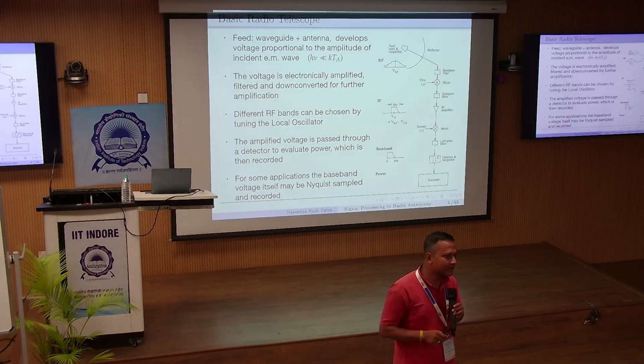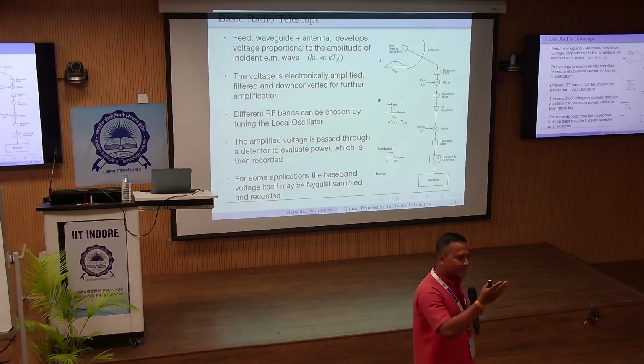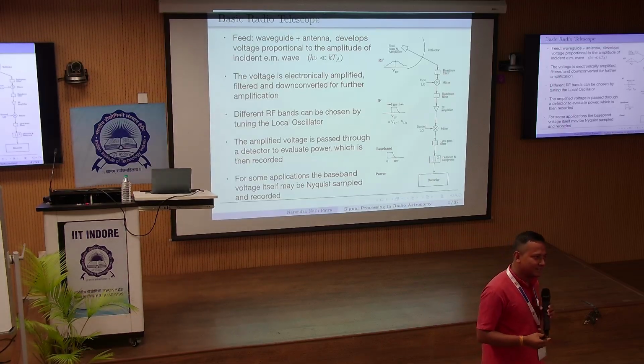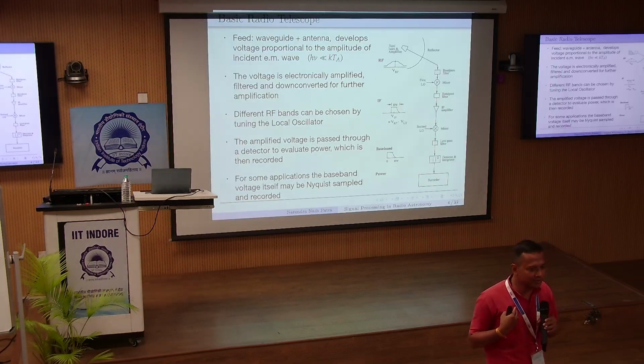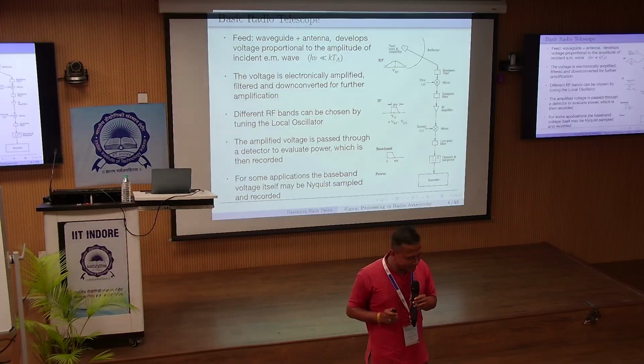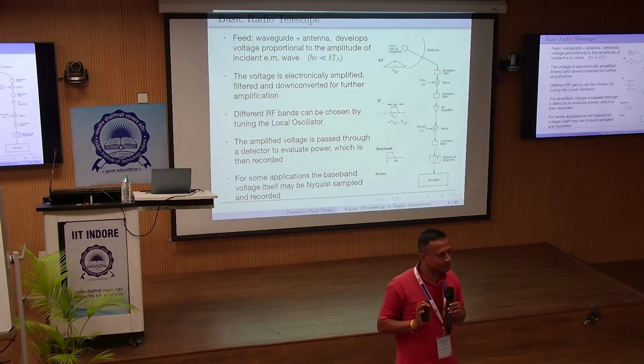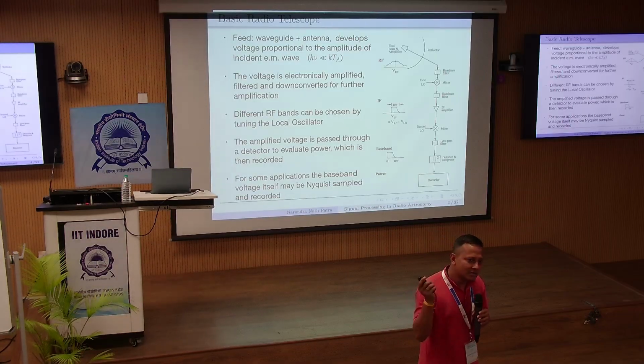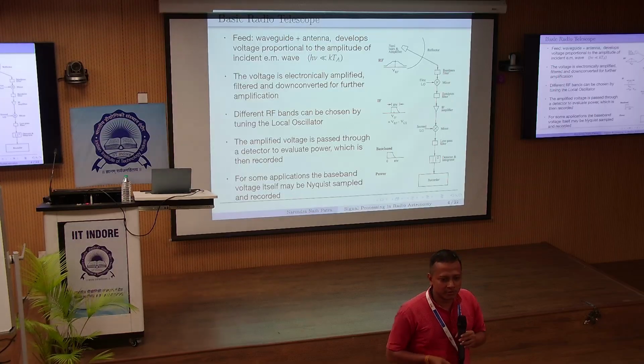If I want to reconstruct it, at what frequency should my sampler be running? Greater than 2.8 gigahertz, right? Nyquist sampling is 2 times the maximum frequency present. Maximum frequency I'm trying is 1.4 gigahertz, right? So 2.8 gigahertz, let's say 3 gigahertz. Okay? What is the speed of the processors in our computers?